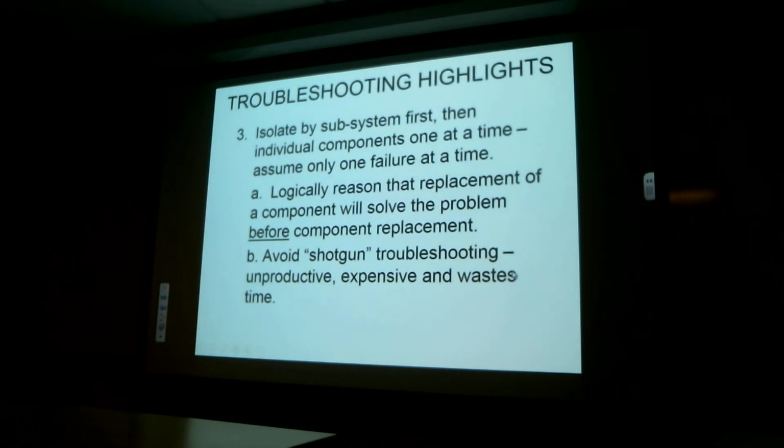Sometimes, things that aren't readily apparent will cause a problem. In manufacturing of aircraft, somebody is careless with a pneumatic drill and they put a drill bit right through a cable, or at least a bundle of wires. So sometimes you find that by twisting a bundle of wires, you've got either a broken or a shorted connection. And again, it was simply caused by somebody carelessly doing things in the aircraft. But again, just haphazardly replacing equipment, you're not doing anything to help yourself.